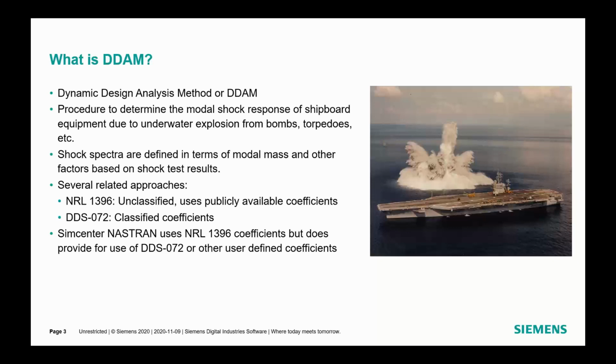So it's a procedure to determine modal shock response of shipboard equipment due to the explosion. And what they did is they developed shock spectra, and the shock spectra were put into some simple equations to derive acceleration loads. The loads were typically put in two classes.